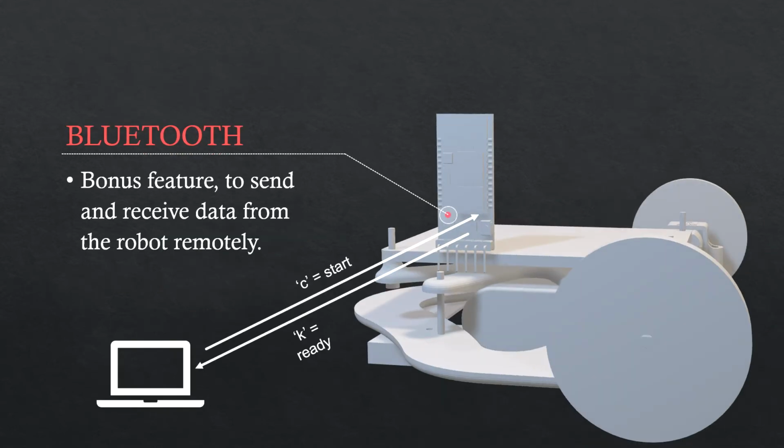For the bonus feature, a Bluetooth module was implemented to significantly extend the capabilities of the line follower. This was connected on an onboard breadboard to the Spark serial receive and transmit pins, which demonstrated the feasibility of a live debug and status update, as well as remote control.